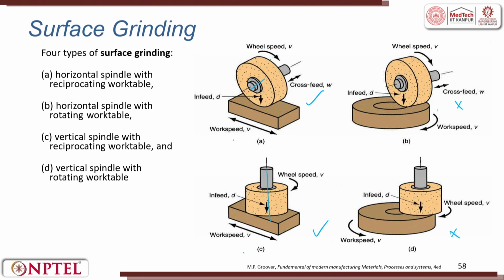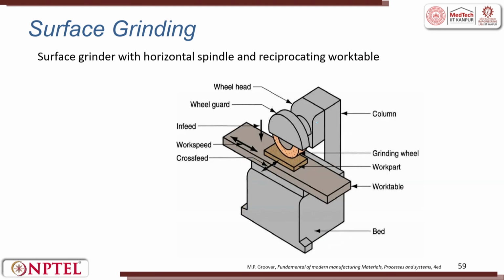The surface of the grinding wheel is used to grind the workpiece. Here the periphery is used; the difference is only rotation, reciprocation, rotation, face, reciprocation, rotation. This is mounted onto a machine tool which is called a surface grinding machine, the same way as you have in a milling machine.